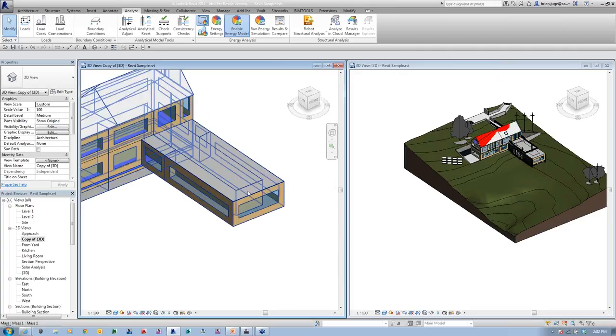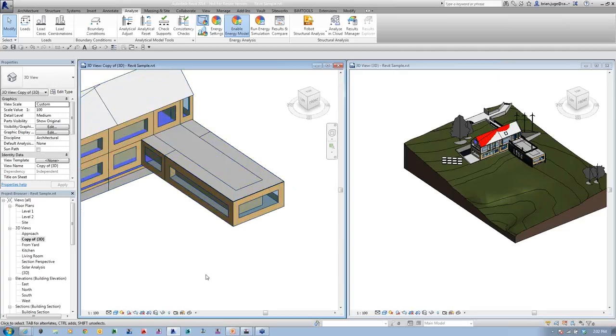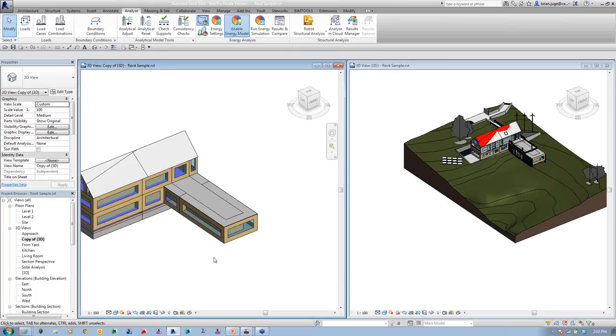You can see right in here, this little volume, that little square inside, it's just the first 5 feet that's counted, and then the core exists inside of there. So if you're doing office buildings, this becomes really great potential, because you'll have a cooling load on the outside of those walls, but then your heating load is being generated from the core on the inside. So that's what we're looking at in these settings in here.